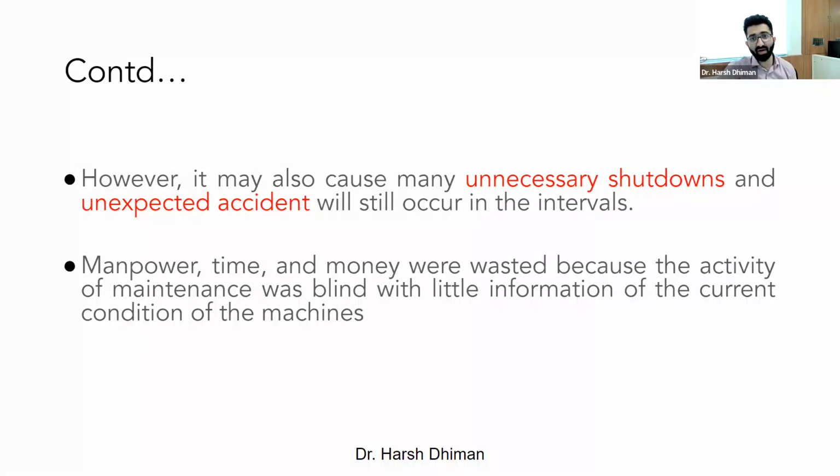And especially in power systems, if I were to speak with proper power system terminology, the capacity factor would go down essentially for a wind farm. A wind farm has a lot of turbines, and each turbine contributes to capacity factor. So if you are in a position to generate 10 gigawatt, but then you have taken out your turbine just because you feel that there could be a fault, your capacity goes down, and essentially you are not generating enough power, and hence the revenue would be impacted significantly. So this is a major disadvantage, I would say, for time-based maintenance.